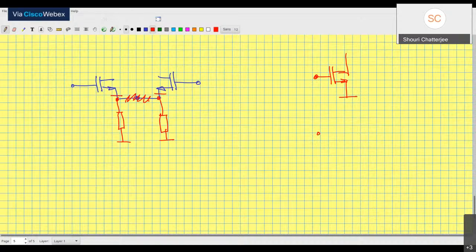In the common mode circuit, this is what you have. And something is there over there, maybe not a current source, right? I want to find out what is that something. Now, if you want no gain in the common mode, then what should this be? This should be a very, very large resistor, right? That's the only way that you will get no gain in the common mode, because then effectively, the source has been disconnected. It's no longer a common source amplifier.